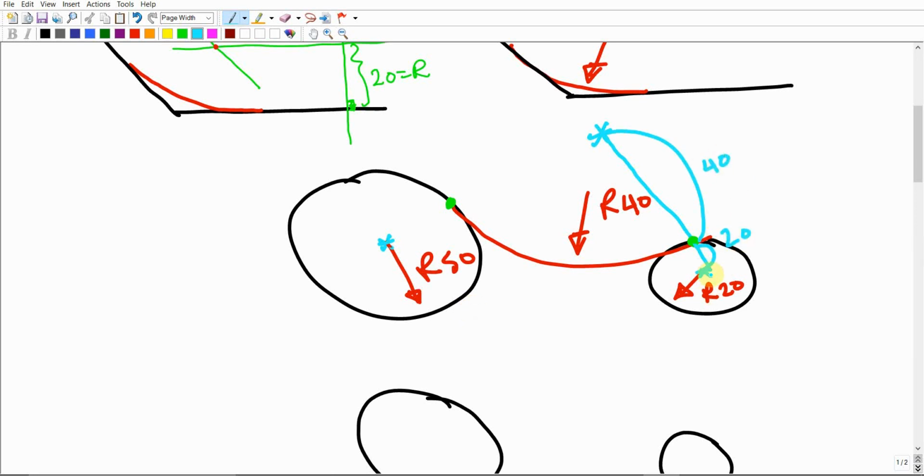So what does it mean? It means that if you fix the metal tip here and open the compass with 60 and draw a curve, this is going to give us the first locus. It should go over the center point that we don't know where it is.